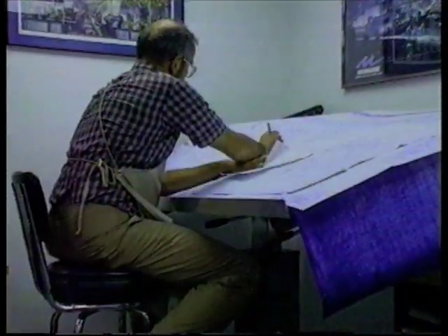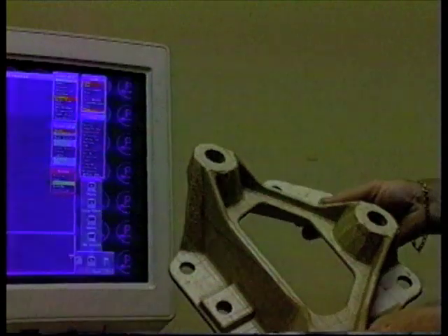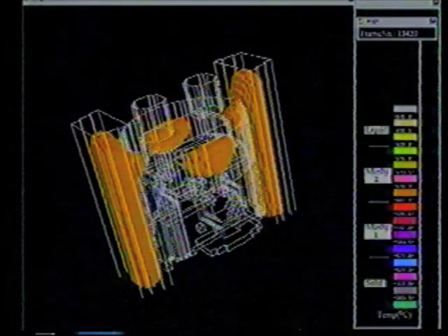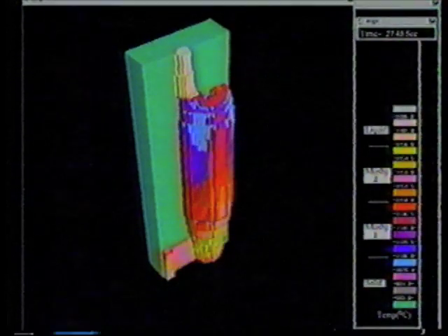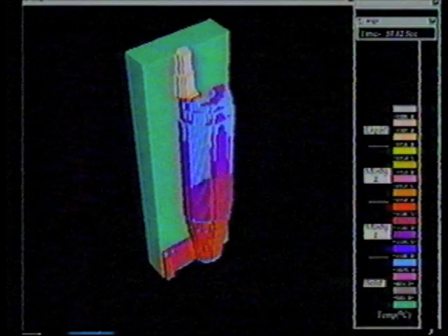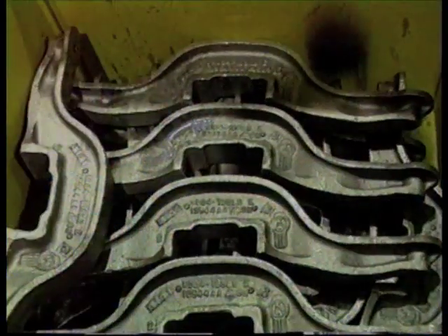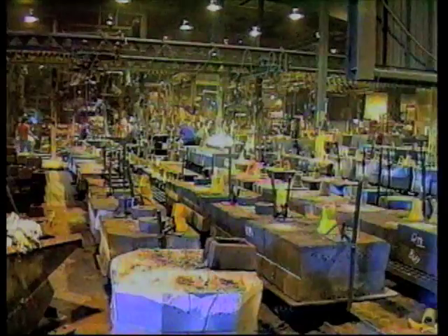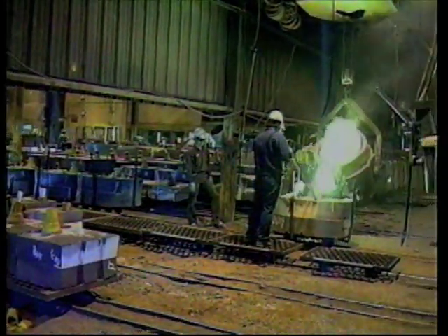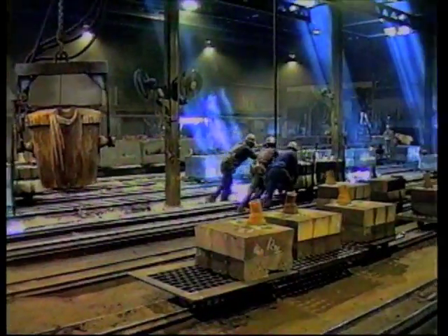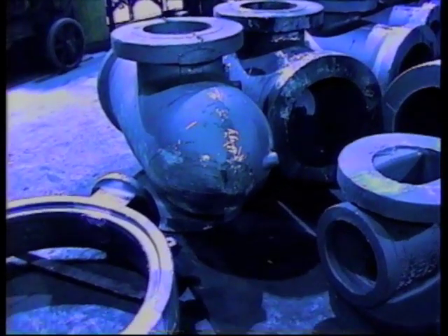The integrity of steel castings has been improved in recent years through the use of computerized analysis. Here is a foundry engineer using a software program designed to help understand directional solidification from the casting to the riser. After casting design is completed and tooling provided, modern foundries have the capacity to make multiple runs in relatively short time frames. It is this repeatability that makes the casting process so attractive. Short runs can be completed in a few days, providing considerable economic benefit to the casting customer.